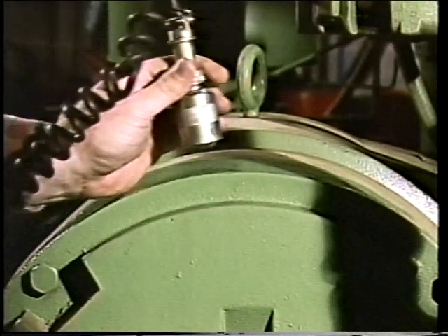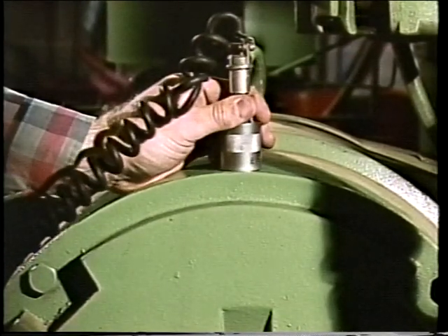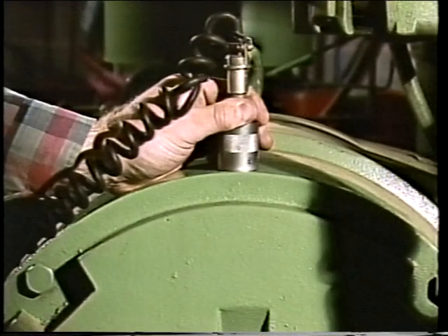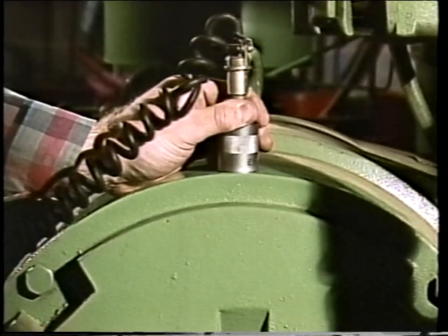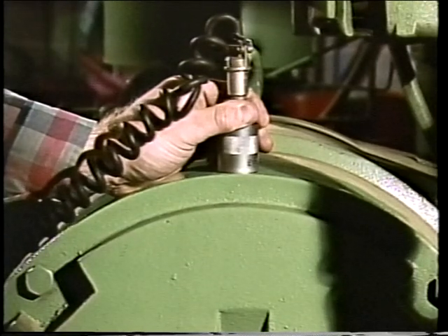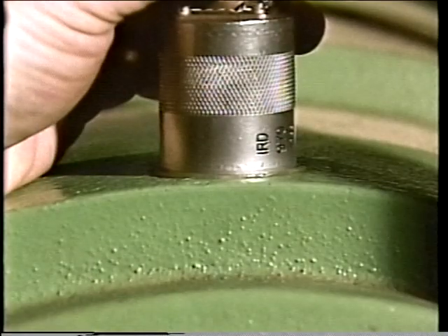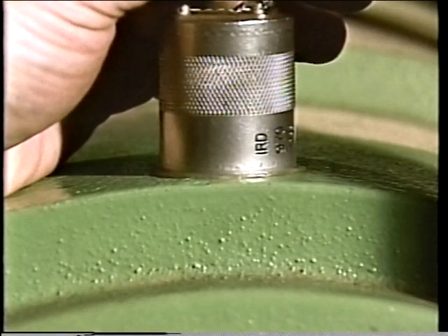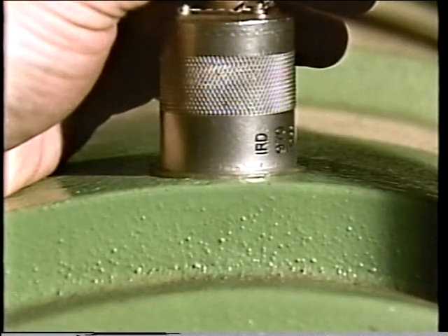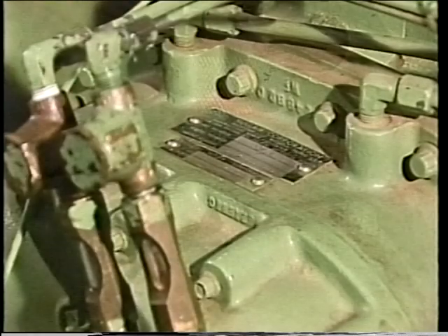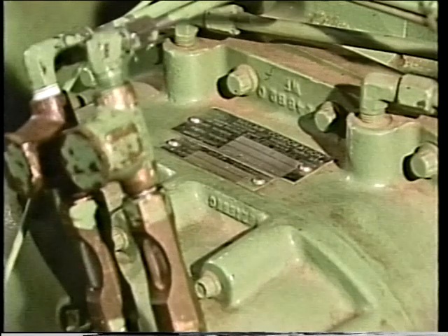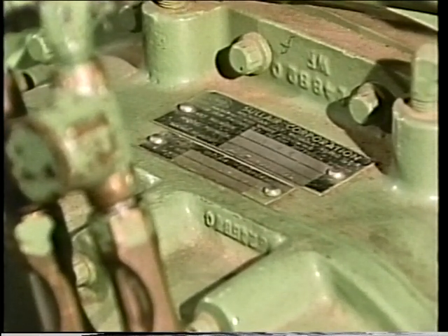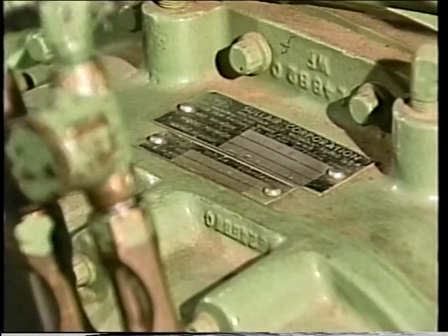In addition to knowing how to attach the pickup, it's also important to know where to position it. A few general rules apply, regardless of the type of equipment being checked. For example, the pickup should be mounted on the bearing housings or bearing caps. This ensures that the pickup will accurately sense the machine's vibrations, since these vibrations are transmitted from the rotating element through the bearings. The pickup should not be mounted on an unstable surface, such as this label. The label could vibrate more than the bearing housing or cap and interfere with the vibration reading.